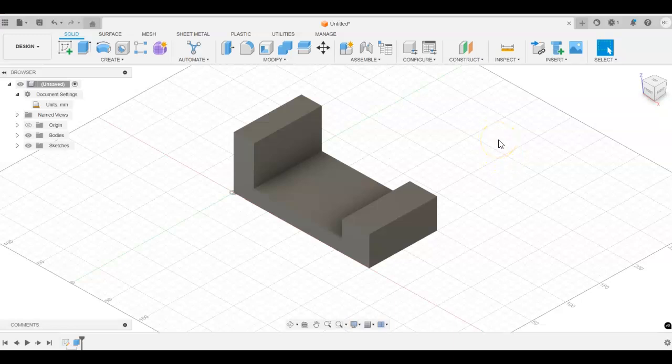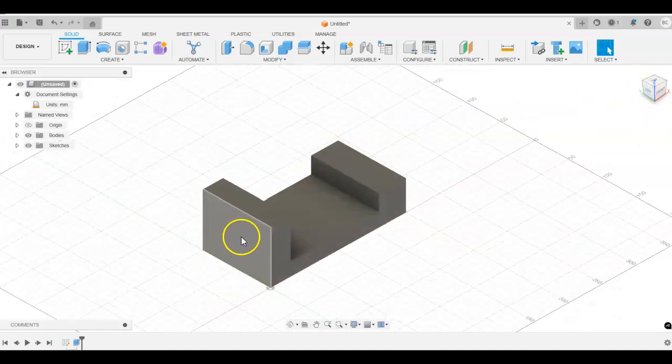All right, so we have finished the basic shape on problem 3-12. So in the text, we're going to add the holes into this drawing now as well. I can either start, we see that there is a hole here on this surface. So we can either model on this surface or we can rotate it around and model on that surface. Doesn't really matter in this case because it's a through hole going all the way.